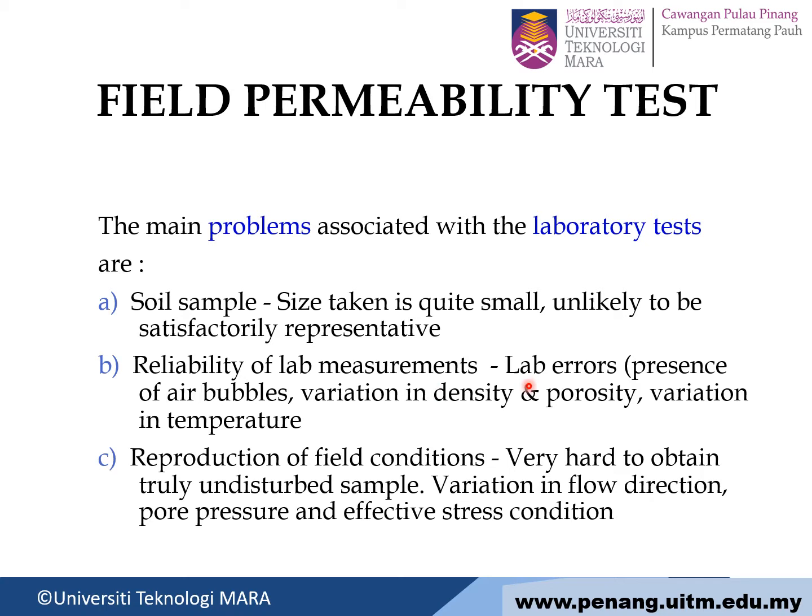It may be affected by lab errors, presence of air bubbles, variation in density and porosity, and also variation in temperature. Number 3, reproduction of field condition. It is very hard to obtain a truly undisturbed sample, and there is variation in flow direction, pore pressure, and also effective stress condition.